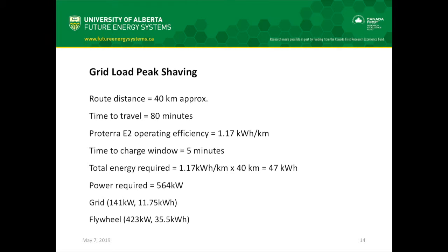The buses that the City of Edmonton is getting have an operating efficiency of 1.17, so it requires 1.17 kilowatt hour of energy per kilometer. And let's assume we have a charge window of 5 minutes. So we need a fast charging system, right?